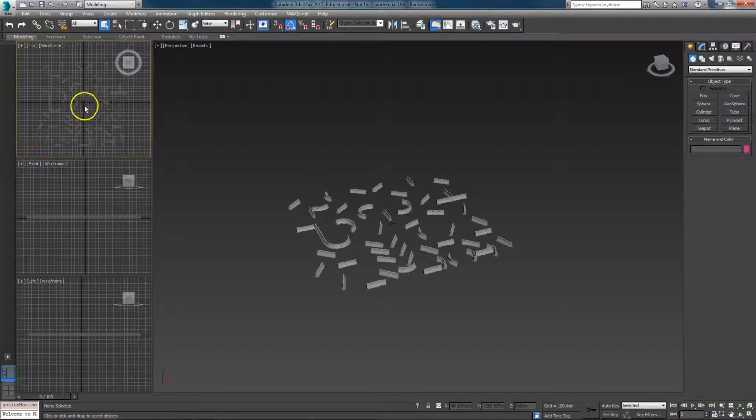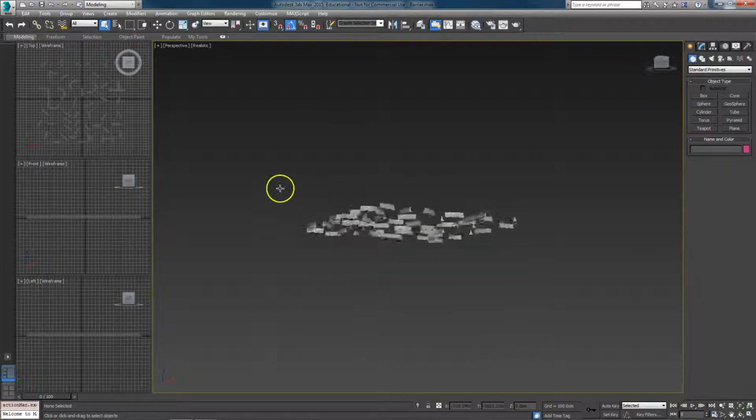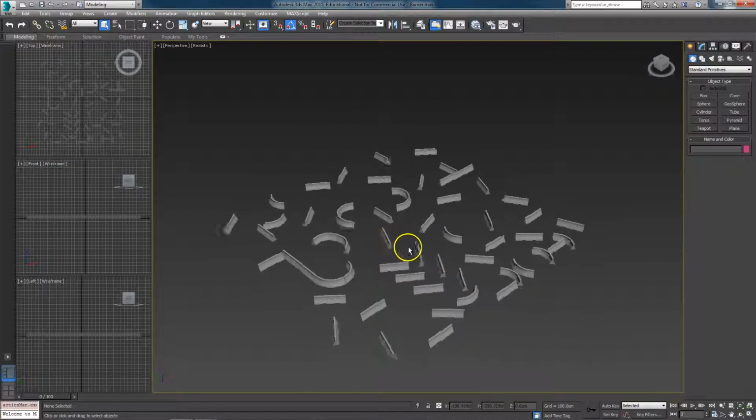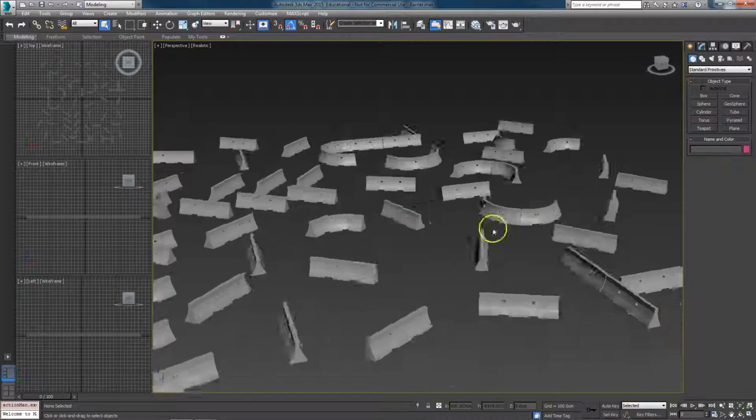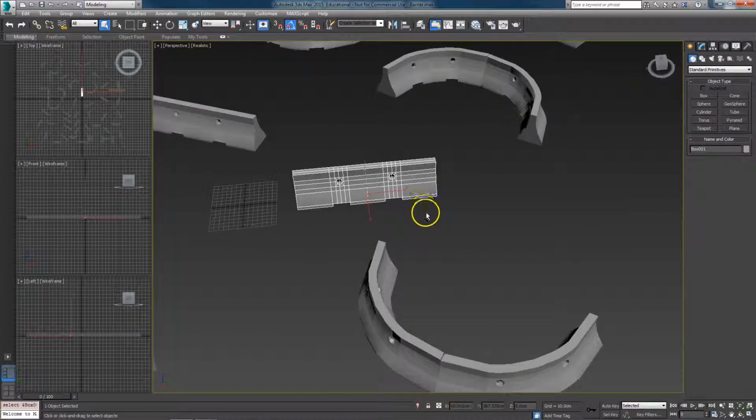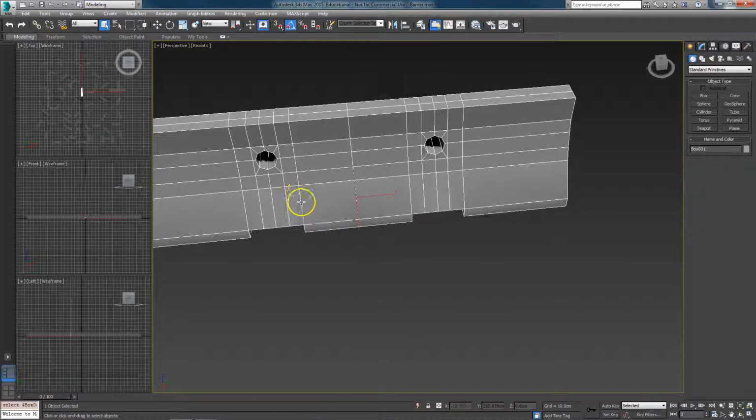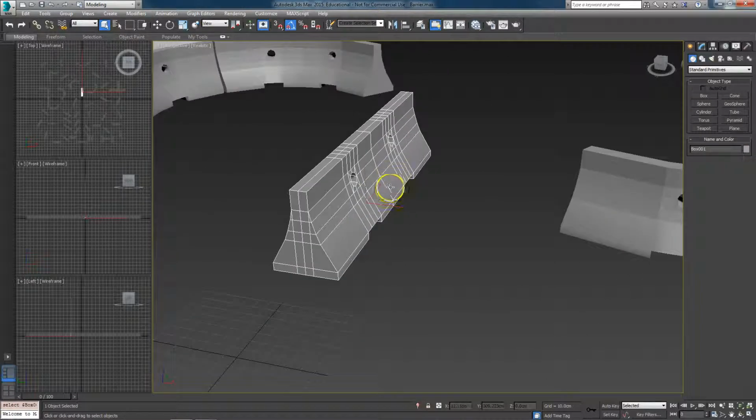So just be mindful that when you're working within this 2D view, if I hold down my middle mouse button, I can pan around, or if I scroll my mouse wheel, I'm able to zoom in and zoom out. These are just a couple things that will help you out. So again, don't use Alt for these. Use Alt for this one right here, your perspective. By doing that, it's going to minimize a lot of issues, especially if I'm trying to come in here and work. So if I zoom in and work in this aspect, I'm able to easily do that.